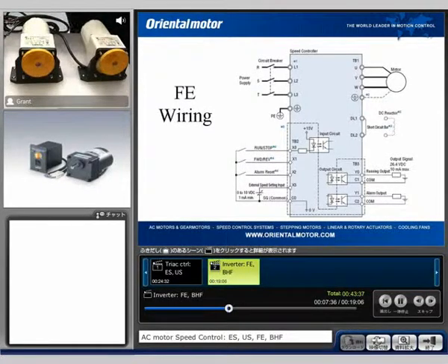I do have a switch mounted here externally so I can reverse the direction of the motors. Now this does have onboard potentiometers to control the acceleration. Right now I have them turned all the way down. So if I go ahead and flip this switch, we can see that the motors reverse directions. Now because this is a 3-phase motor, these motors can practically reverse directions almost instantaneously.